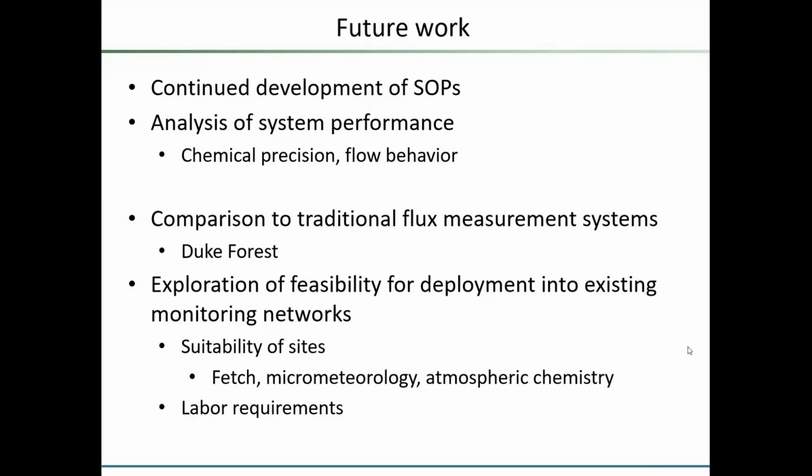Okay. That's right. And we're hoping that maybe by using both the traditional aerodynamic gradient technique and the modified Bowen ratio that we can extend that temporal coverage. So maybe there are some periods where the aerodynamic gradient approach fails because the stability corrections are too large, but the heat flux and the temperature gradient are well resolved, and we can use the Bowen ratio technique. So there will also be some comparison of those two approaches that is necessary.